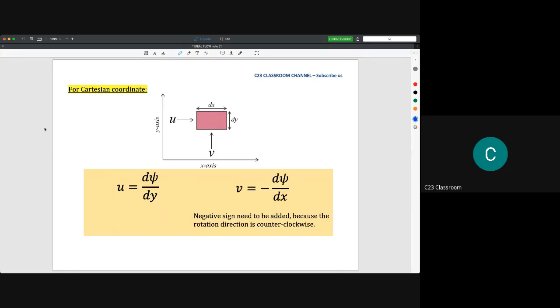That's why in fluid mechanics 1, for example, if you had a tank here and you have a pipe, whether it is upward like this or downward like this, or if it flows backward like this one, the flow rate here will always be positive, because volume flow rate only needs to be calculated as a magnitude. So the direction of flow rate or volume flow rate is not counted.